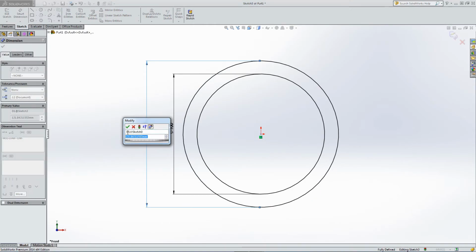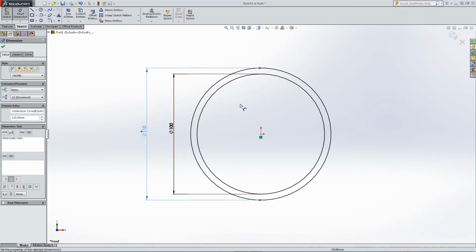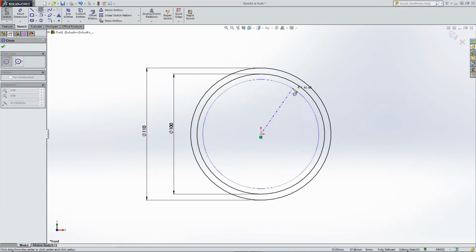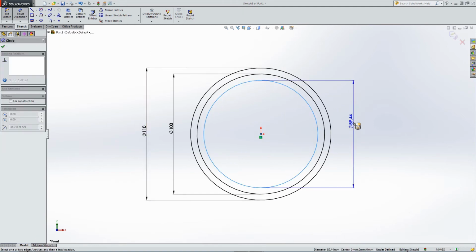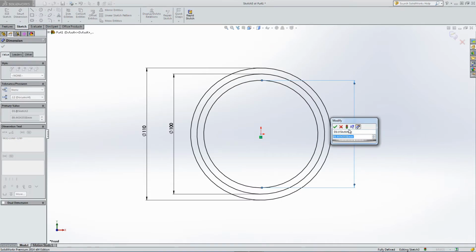This is basically a template sketch that we're forming at the moment. So the addendum circle, and we'll give this an arbitrary value. This gear is going to be equation driven, so when we're finished we can modify certain variables and have the whole gear change, and we'll finish by animating the gear or a couple of gears interacting.